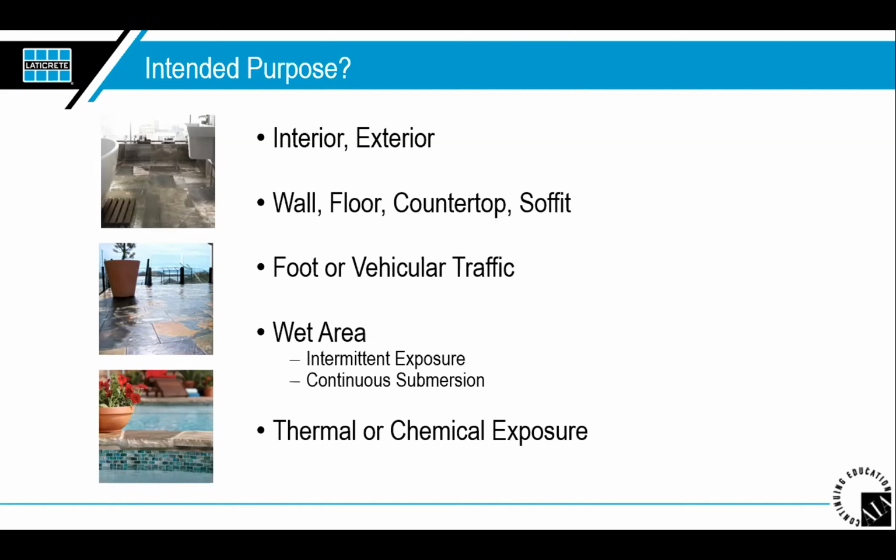So that's what we're talking about: are the setting materials able to convert from foot traffic to a car dealership, or a car being driven in there? Wet areas, for example, require special attention so that you can prevent any type of leakage or water damage. And a big thing for thermal expansion is the exposure to sun and heat, and it's often overlooked in the application of tile and during the life of the installation. But use of tile in areas exposed to chemicals and heat or sunlight is going to play a factor in how long the installation actually lasts.